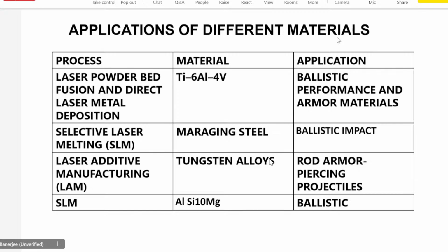Why are the challenges inherent? The challenges are inherent because whenever one layer is solidified and then another layer is solidified, the solidification rate is different. When the second or overlying layer is there, the heat transfer is already going through the material which is already solidified. This thermal conductivity is a function of temperature.